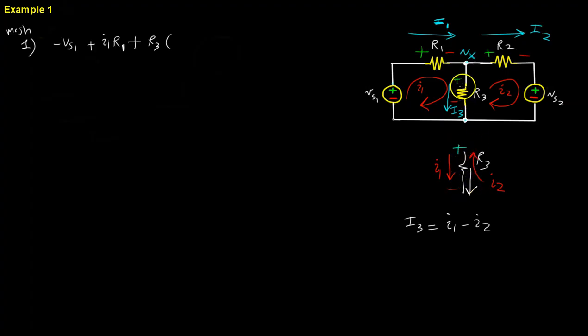There's a net current going from positive to negative based on what we chose per the passive sign convention, and because of that, we're going to say that I1 minus I2 is going to be the net current that's going to flow this way. The assumption here is that I1 is greater, and so the difference between the two is going to be the current flowing downwards.